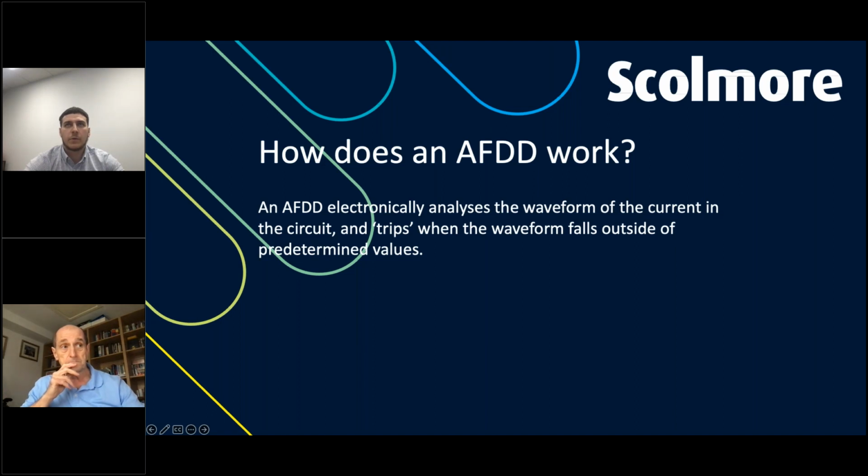Yeah, I think if we go back to the point I was making a minute ago, where we start doubling them up and using them like an RCCB, we imagine we've got a split load board and we've got one on the front end. If we've got one of those signatures on various different circuits, you could see an unwanted tripping or an unwanted operation of these devices happening, and hence the reason why they need to be singular when it comes to individual circuits.